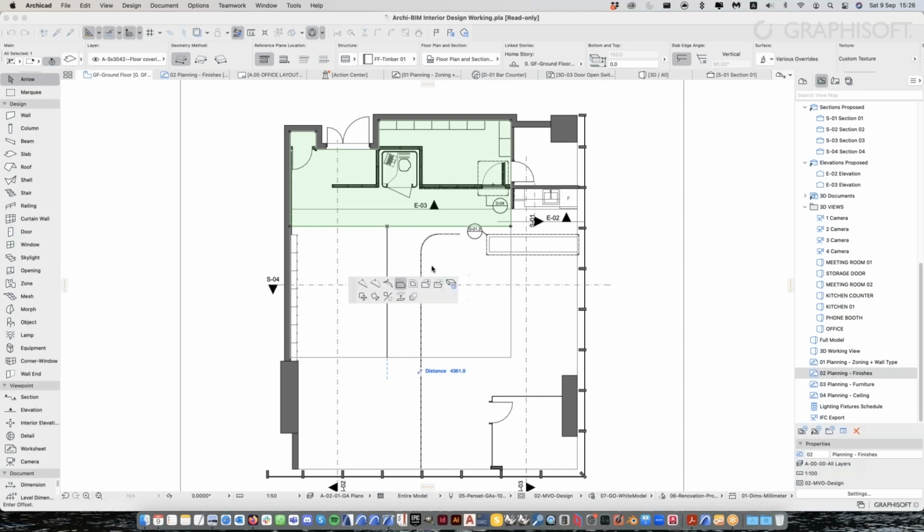You can move it around if it's in your way by click and holding the left of the palette and move it to where you are and release. So this is the edge. So you click on the edge, it will show a pet palette. And these are the editing options. So now I can maybe select the offset edge option.